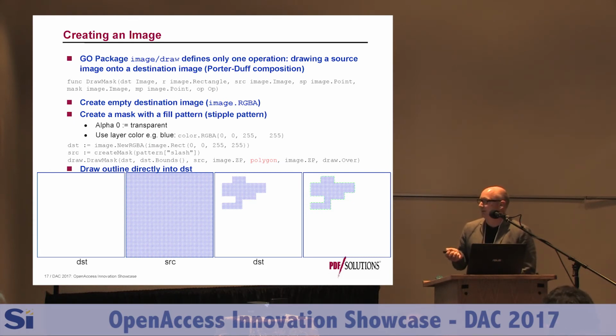If you think about Cadence or any other EDA tool, they have this stipple pattern for fill and for outlines. So this is your fill pattern and color. That's what the user gets to determine. Right now I'm reading the display DRF and just reading everything Cadence has, and I'm copying exactly the same definition. Luckily, I can just dump it in as is. I can show you later. I can use the exact same definition of the stipples as Cadence uses. It's just a matrix of ones and zeros for transparency versus non-transparency.